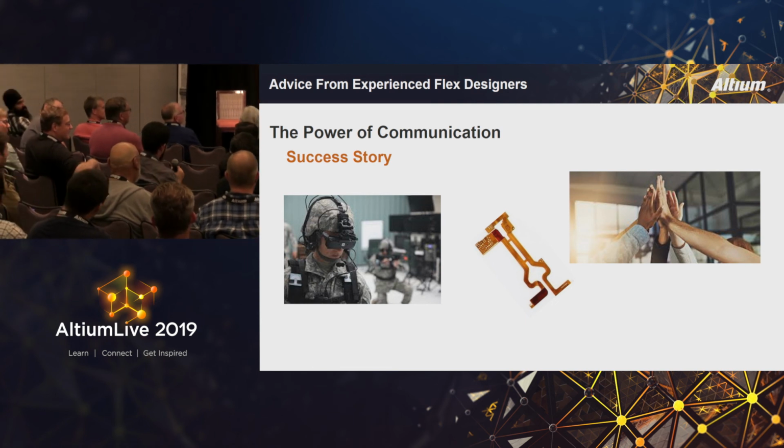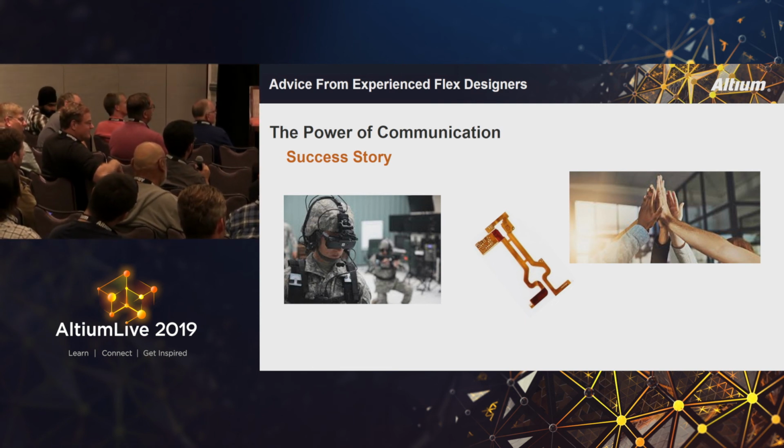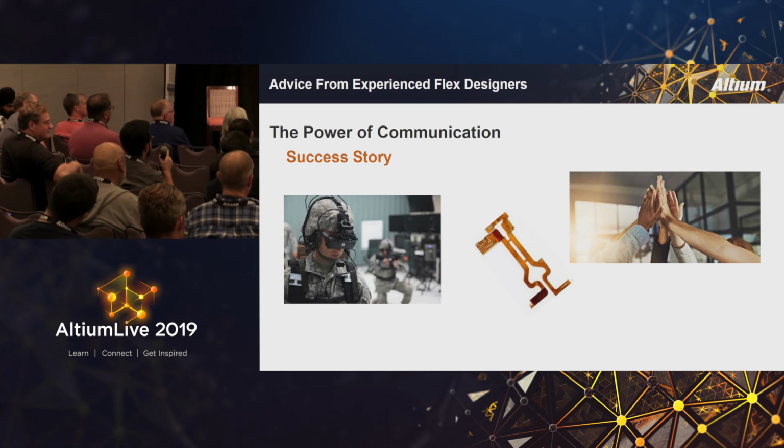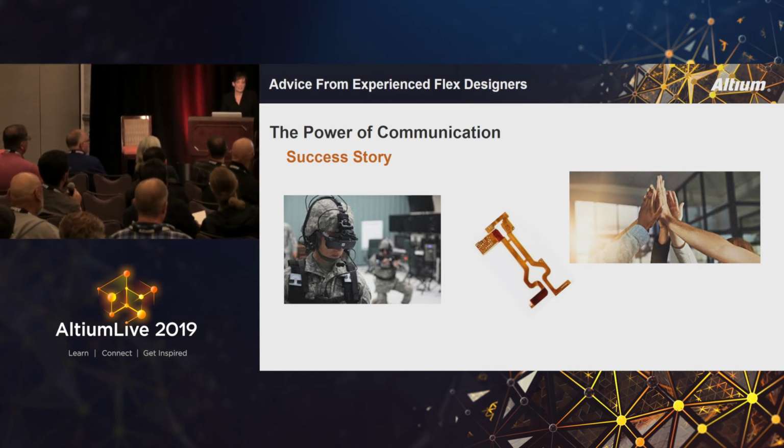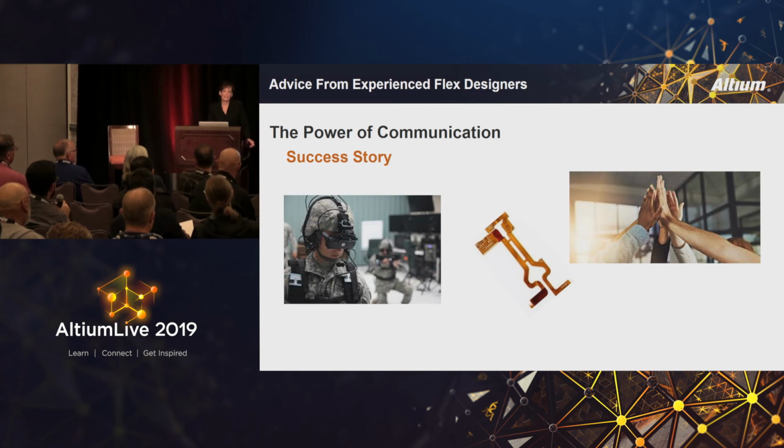I had a question. We do high temperature stuff, so what kind of rigid flex would you recommend for high temperature? We do 180. Probably adhesive-less. Is that what you're asking? What type of flex materials? Yes, because we do 180C. Yeah, in the laminate, I would go with an adhesive-less laminate. The adhesive material is going to be the first thing that's impacted by heat.